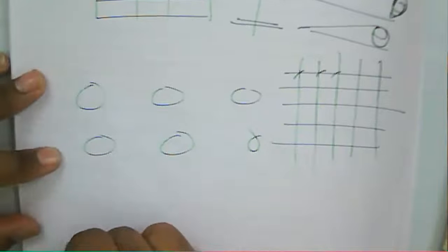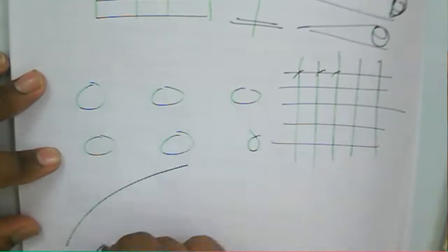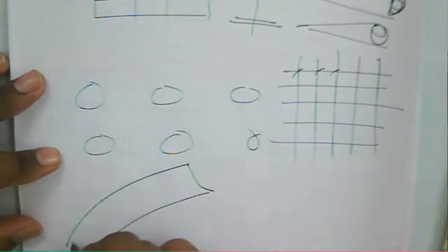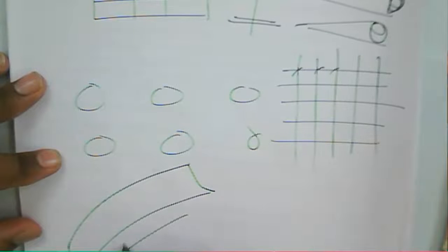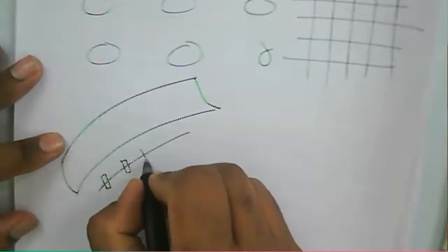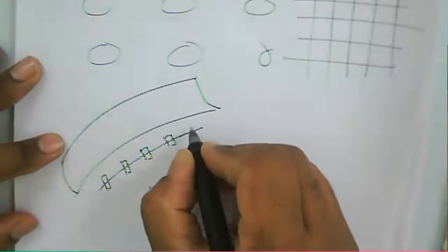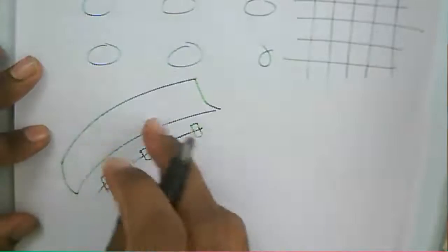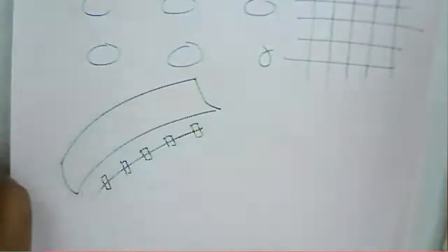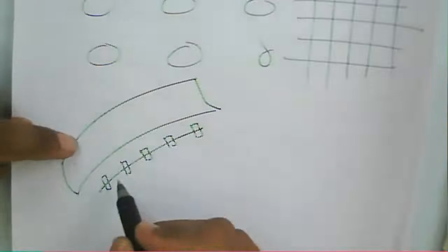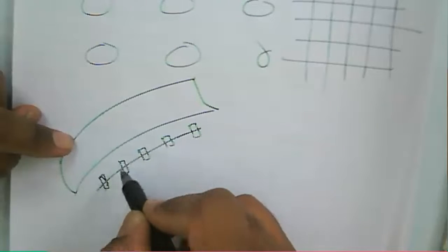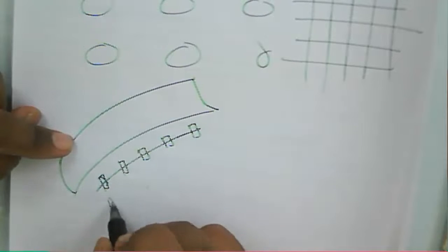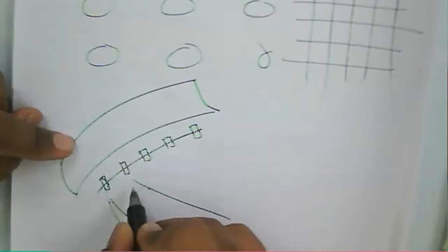Or we have a half cylindrical structure, and in front of its axis multiple reflectors are used, which can be dipoles placed at the center axis. If you cut a pipe in half and place multiple antennas at the center of that pipe, then the beam coverage will be different for this antenna.